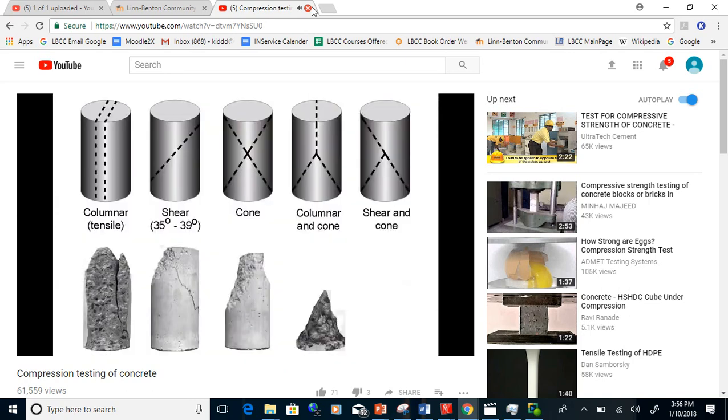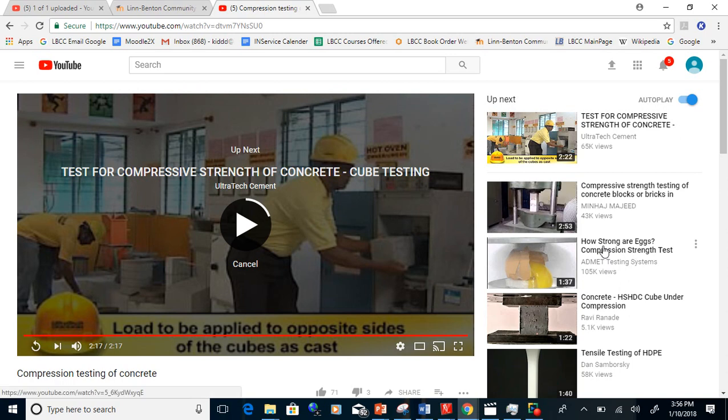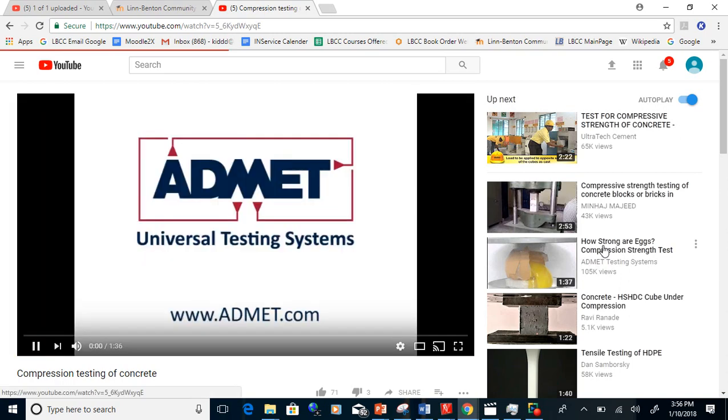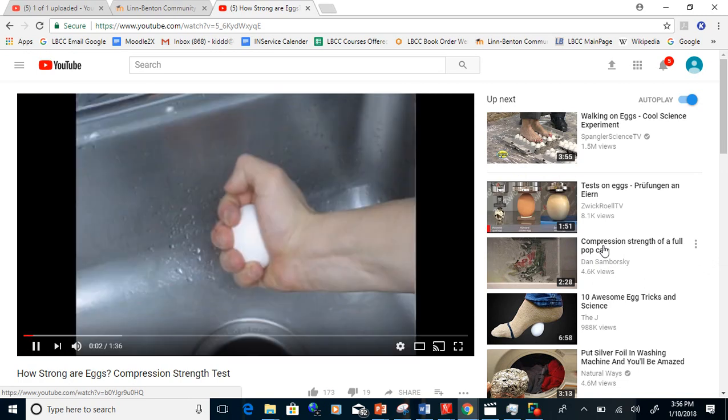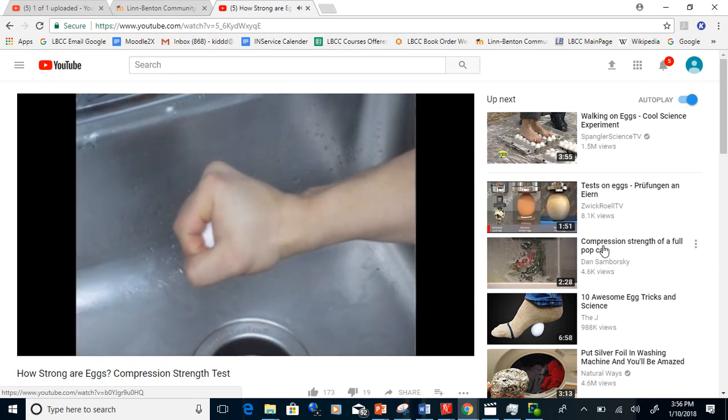It actually takes forever to reach full strength, but 28 days was the old standard. These days, with all these different admixtures, I don't really know, but for pure concrete, 28 days was the standard for getting it close to its ultimate strength. Isn't the ultimate strength actually forever away? Yes, it continuously gains strength. It's an exponential curve.